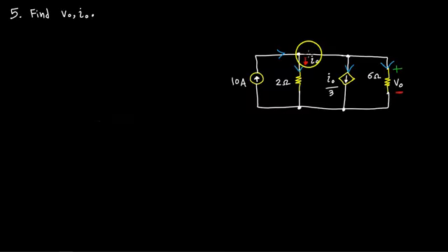currents indicated, and I'm doing this because it makes sense in the alternate form to say I have 10 amps of an independent current source going in this direction, then I have some I0 going in that direction, and this matches nicely with the convention. Don't worry if you pick the current to be the opposite of what I'm doing. The correct answer will manifest itself if you do the algebra correctly and consistently. No matter what sign you pick, you must stay consistent with the relationship. What matters is the algebraic relationship between these quantities, and it has to be kept consistent with whatever sign you choose.